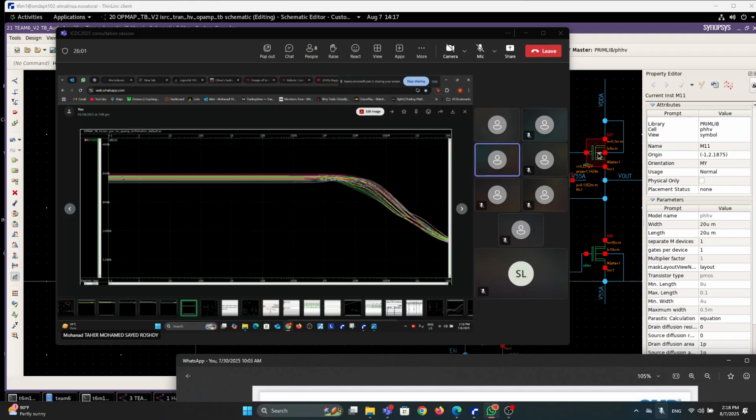I confirmed with Mr. Eddie before. He said we measure at 1 hertz, as the minimum frequency PSRR needed. This PSRR is for the power supply, so we inject noise into the power supply with the noise frequency from 0.1 hertz to 10 gigahertz.